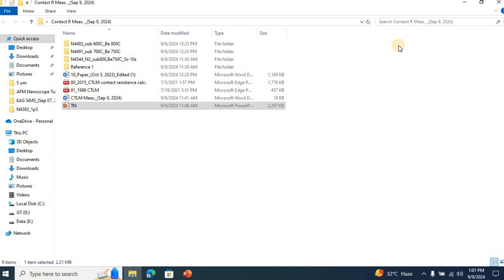You might have used nickel gold, or titanium aluminum nickel gold, or titanium aluminum titanium gold. You can vary the thicknesses, or you can vary materials. You might like to use platinum palladium gold for wide bandgap semiconductors. And you might like to play around with the annealing temperatures and the annealing time, etc. So these are the parameters that you can change in order to optimize your contact resistance.